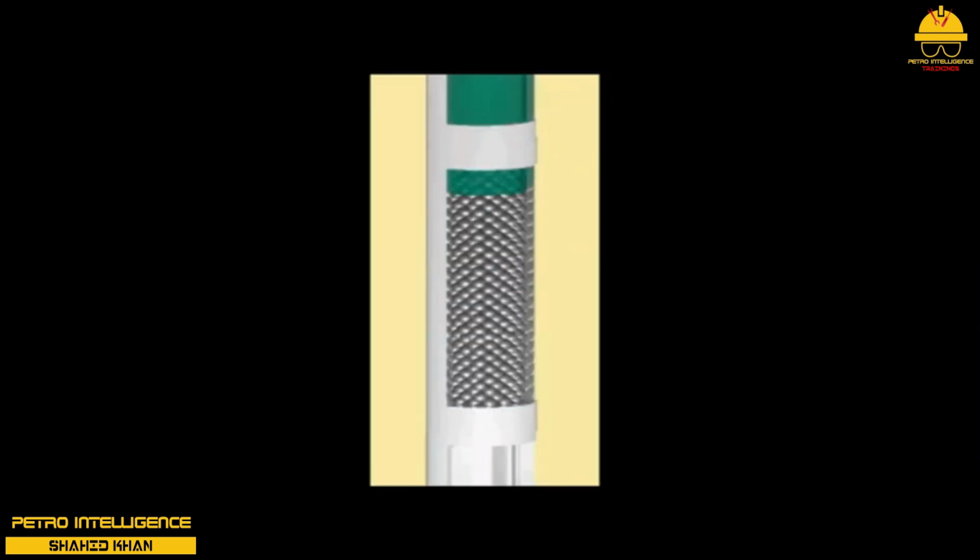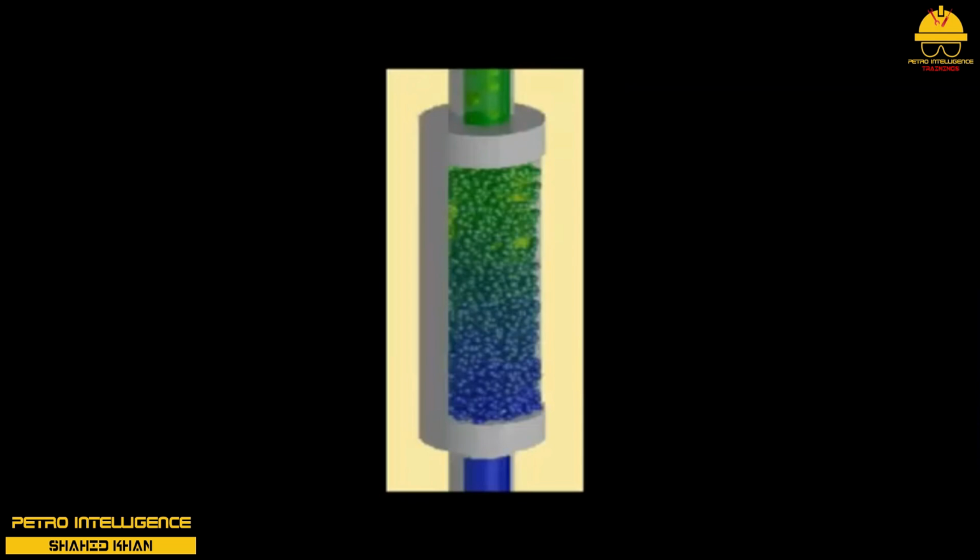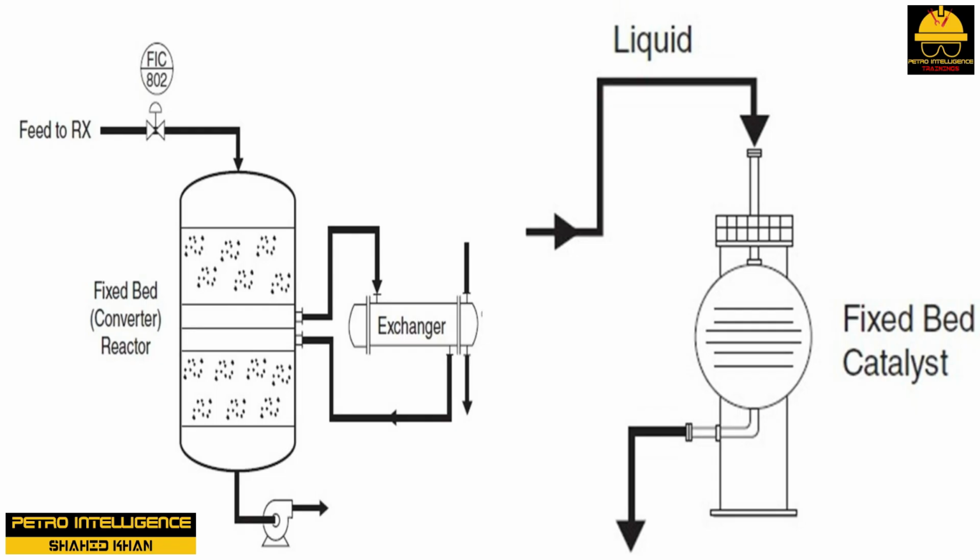Fixed bed reactors are designed with an inlet line and an outlet line, catalyst bed limiters, distribution and support grids, catalyst removal hatches, process variable instrumentation, and safety systems. Many converters have a method of removing or adding heat from the bed. The main reasons for arranging the packed beds in a configuration other than the large single bed are to provide better heat transfer, to provide better distribution of the reaction mixture through the converter so that the gas or liquid feed will not channel through the bed, and to reduce the amount of force applied to the packing at the bottom of the bed.